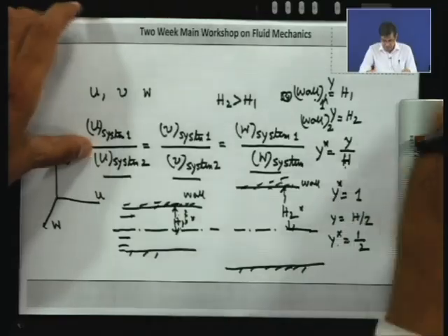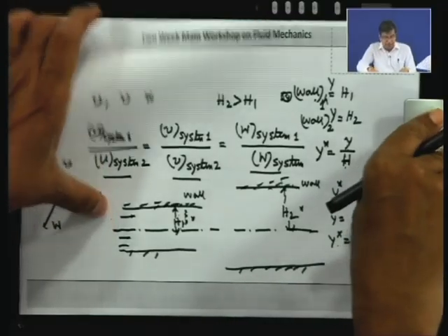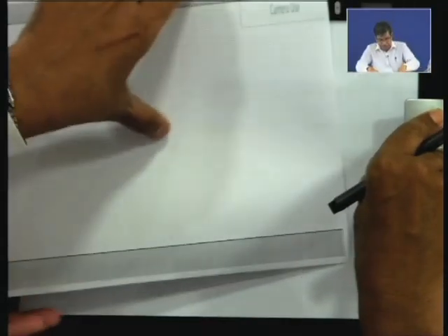And as you know, an impermeable solid boundary represents a streamline because there is no flow across the boundary. So for kinematic similarity to be maintained, the boundary, being one of the streamlines, has to be similar. Again you see that geometrical similarity is a prerequisite or necessary condition for the kinematic similarity. Okay. Next we will come to dynamic similarity.